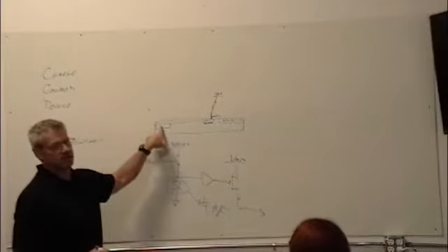And so if you look at it from the side, you've got a diode formed here that I think was a P plus plus. And then you had this setup. So this guy was always open to light. I'd open my shutter, I'd let the light in. See, with the full frame imager, if light's still on it, I'm still absorbing light while I'm shifting things out, so I have to close the shutter. Mm-hmm. So I'm still limited to mechanical speeds.